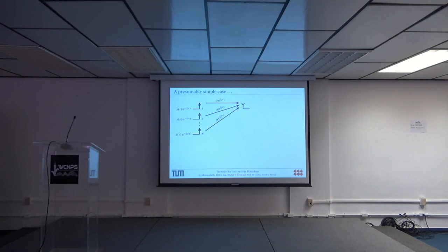Let's now look at the multi-antenna case. The standard thing is, if we have an antenna array with n antennas, and there is one receive antenna, and assume that they are all close by, such that the distance between each transmit antenna and the receive antenna is almost the same, only the phase of these different paths will be different, and I can assign a beamforming vector which compensates for that, such that I get maximum signal at the receive antenna.